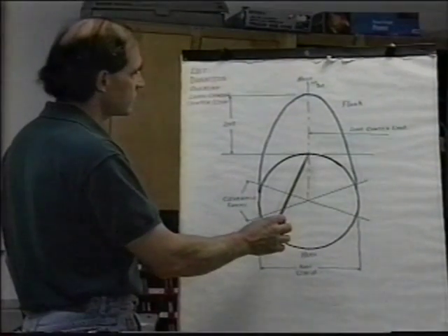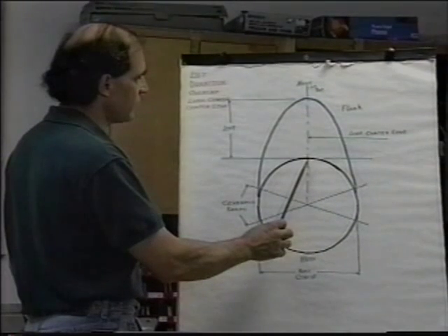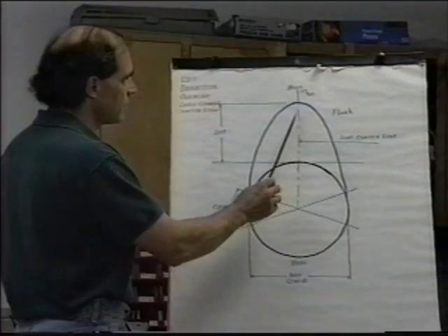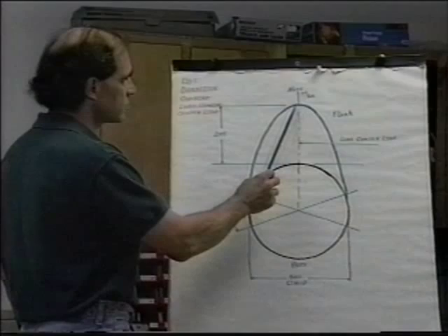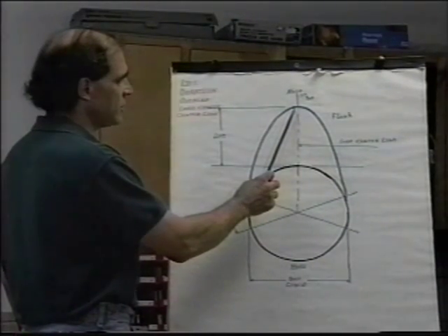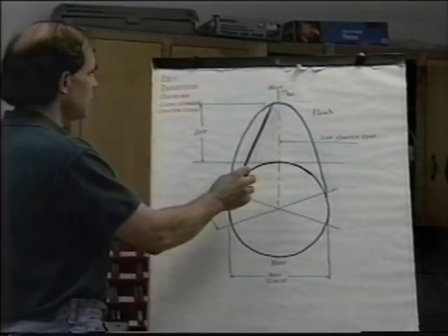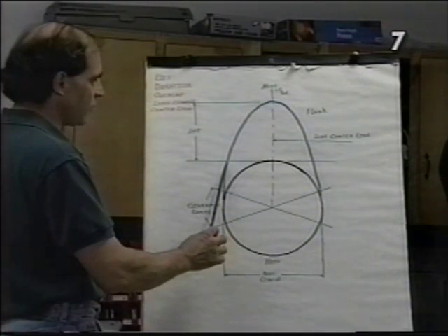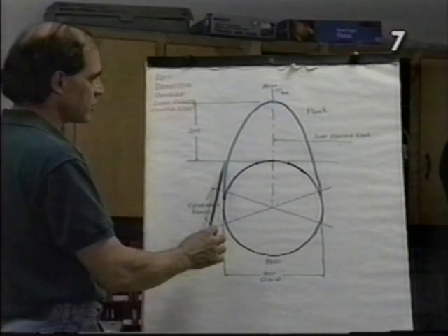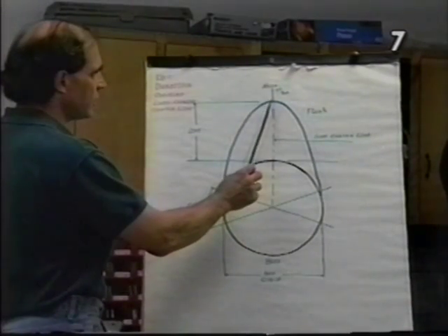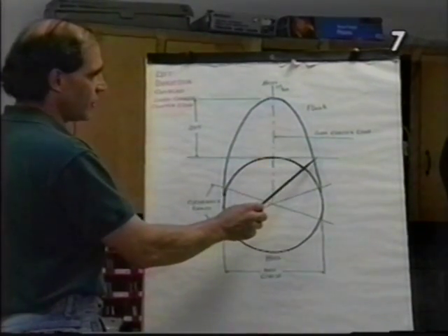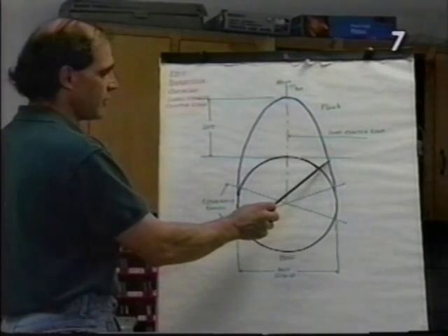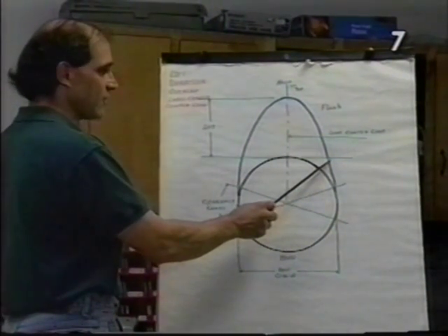Total lift is the dimension from the top of the base circle to the peak of the nose, as measured in thousandths of an inch. Duration is the total amount of time that the valve is actually opened off the seat through full lift and back to the point where it is closed and down on the seat, measured in crankshaft degrees.